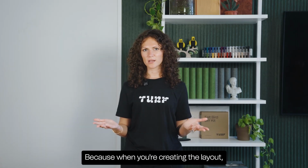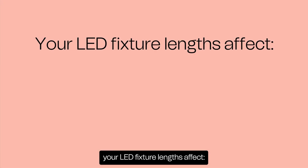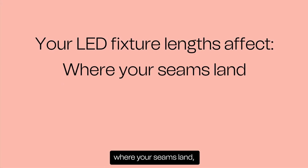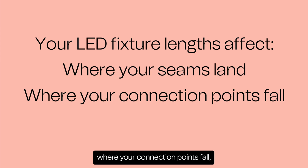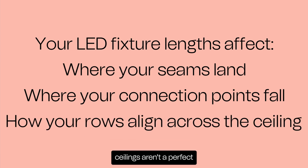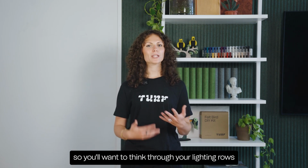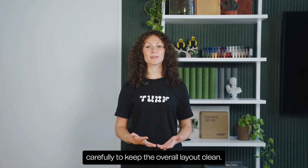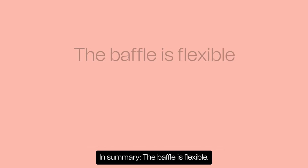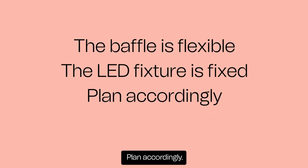Why does this matter? Because when you're creating the layout, your LED fixture lengths affect where your seams land, where your connection points fall, and how your rows align across the ceiling. In most projects, ceilings aren't a perfect multiple of your fixture size. So you'll want to think through your lighting rows carefully to keep the overall layout clean. In summary, the baffle is flexible, the LED fixture is fixed, plan accordingly.